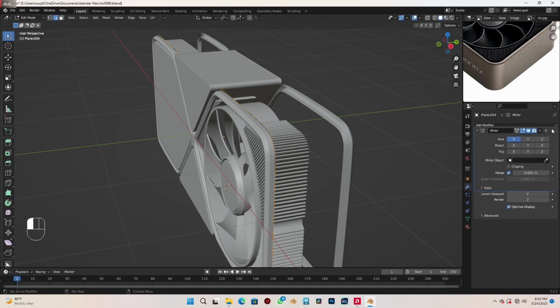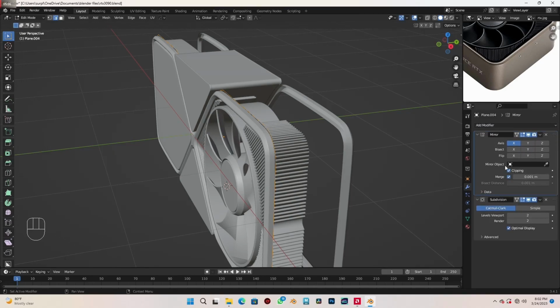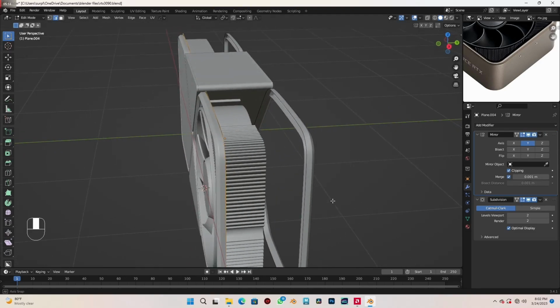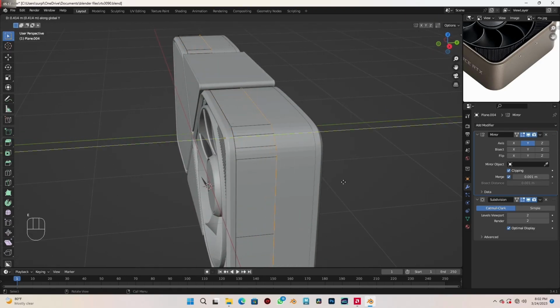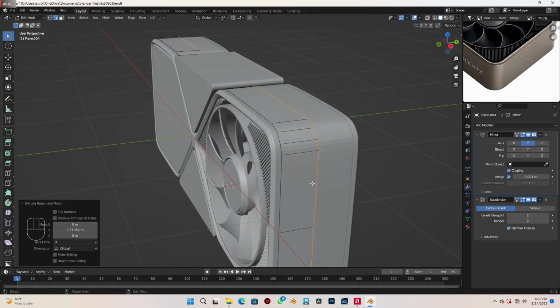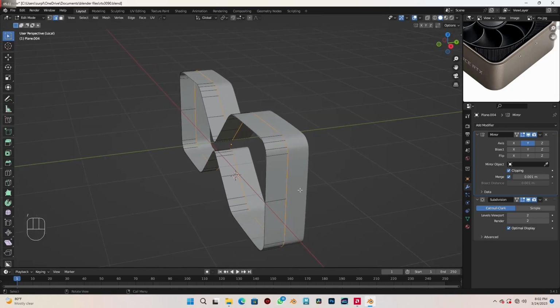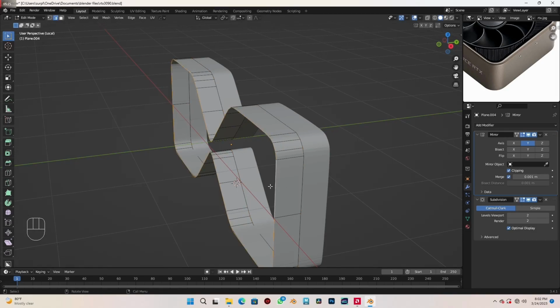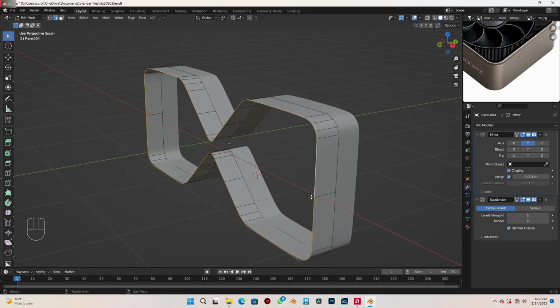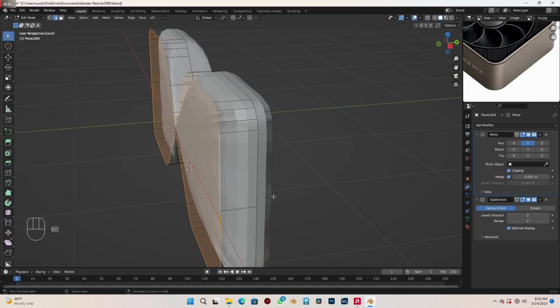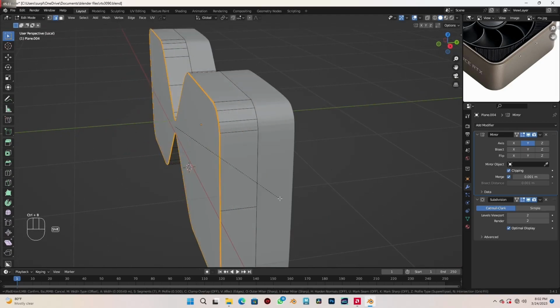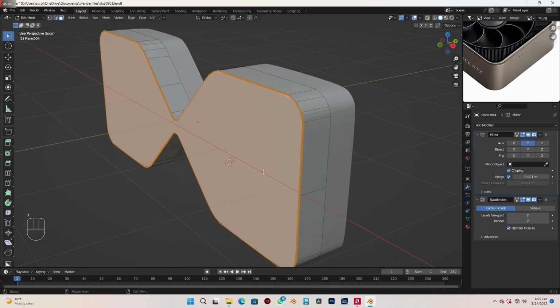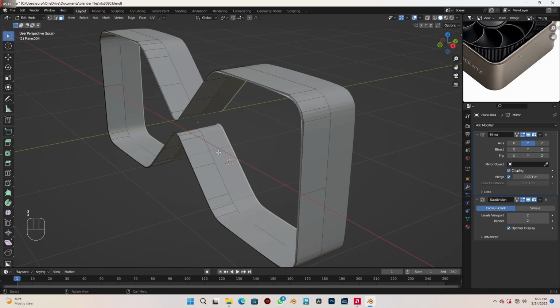So I'm going to add in a mirror. Let's drag that up, enable clipping and mirror it over the y-axis and uncheck the x. And I'm gonna extrude it over here till it clips. Okay, let's go into local view and selecting all these edges, I'm gonna press F to fill that, and let's bevel that something like this. Okay, select this face and delete it.